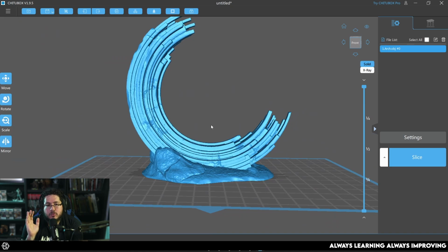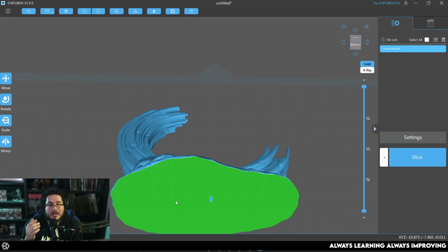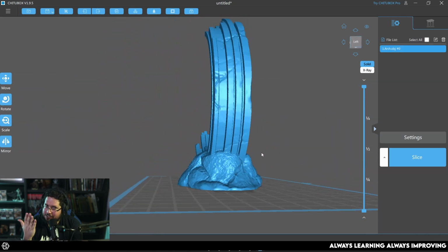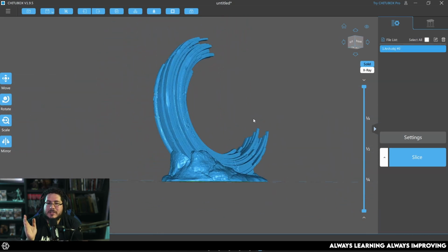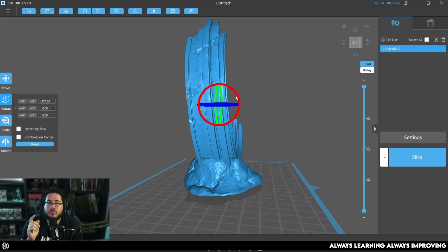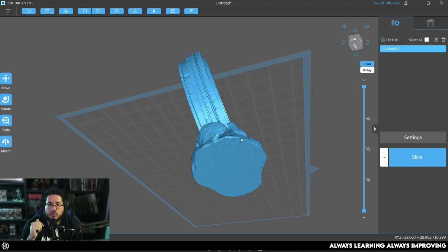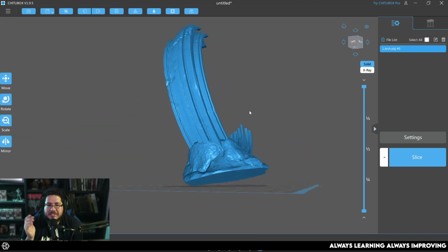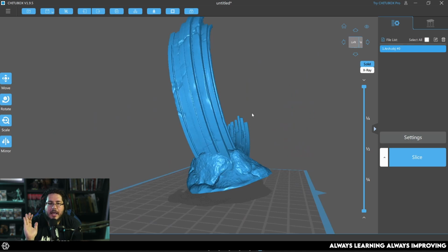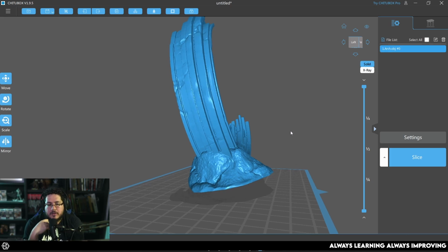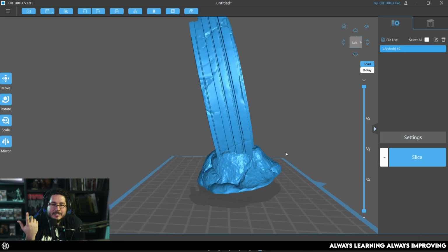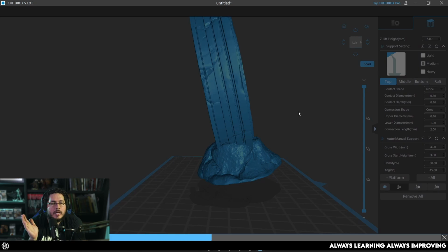But you give yourself, again, another sort of cushion by doing the supports on the back of the character, so that if you get some damage, it's not going to be as visible. So it's kind of like UV seams where you want to hide them. Well, supports are a very similar thing. You want to hide the supports. So in this case, I'm going to tilt this 15 degrees. In this case, it's more than enough. That removes a lot of the suction, or a lot of the tension that you're going to get from pulling such a big piece from the build plate. And yes, it's going to require a little bit more supports, but it's not that big of a deal.